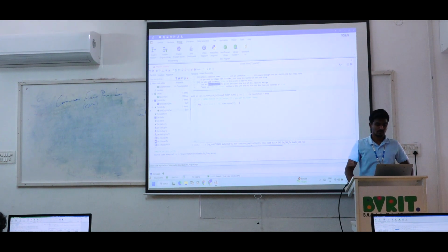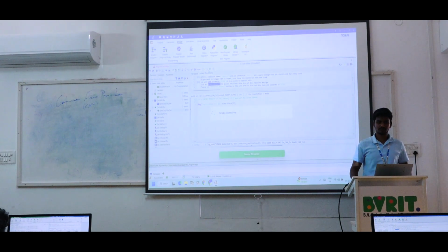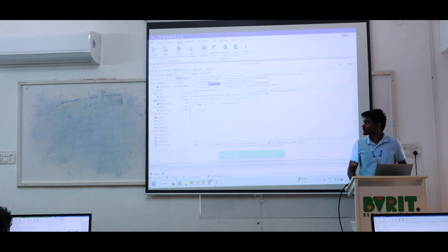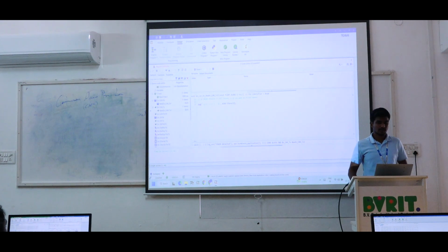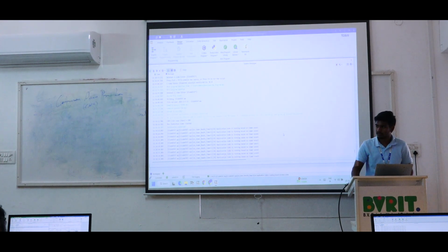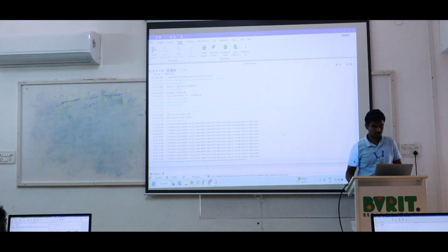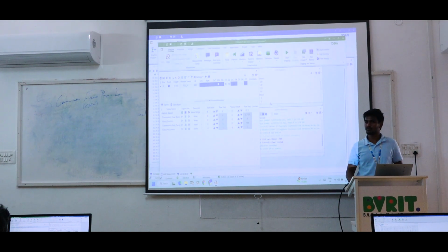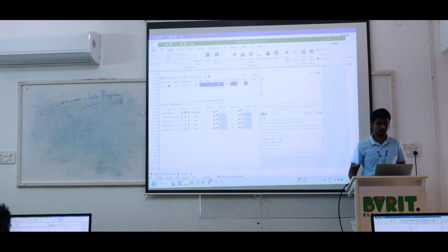Okay. Now we just compile this code, and then we have to start the scripting. After starting the script, go to these messages. It is showing only the vehicle speed. You are not transmitting. So parallelly, we have to transmit it with a new window. We have to open a new window.